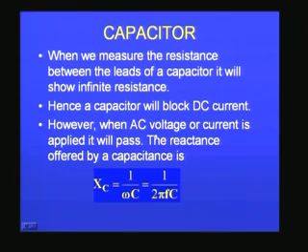Hence, obviously the capacitors will block DC, direct current. However, when an AC voltage or current is applied, the capacitor will offer some reactance, as it is called. It is not resistance, it is reactance, because it is only responding to time varying signals of voltage and current, therefore it is called reactance.